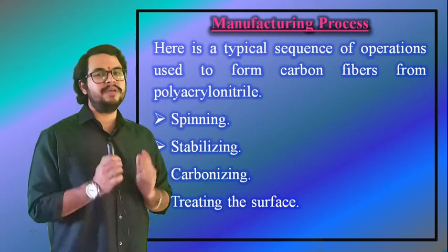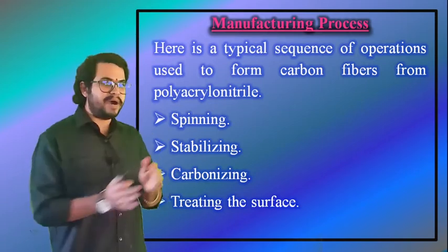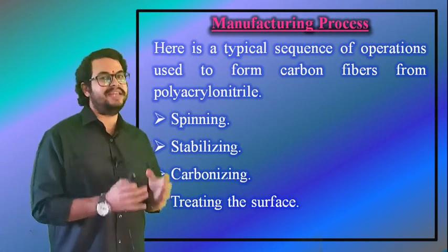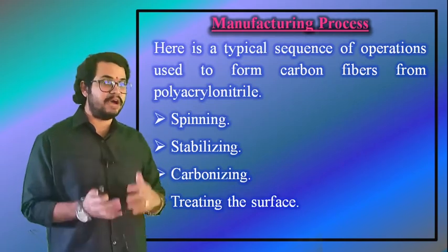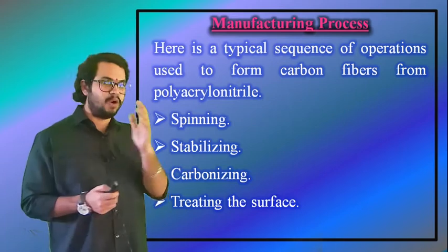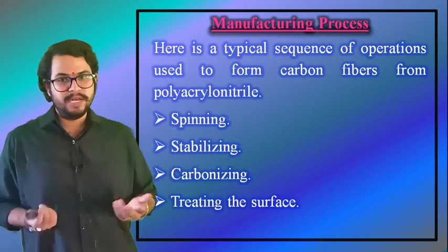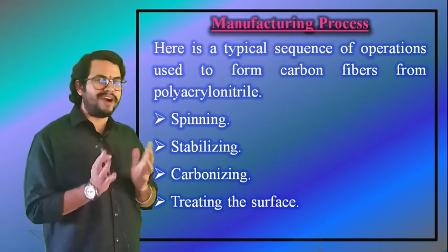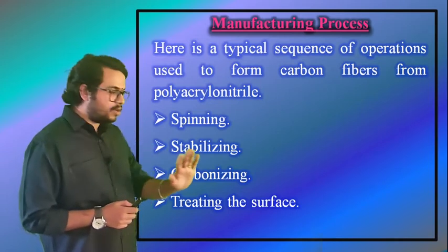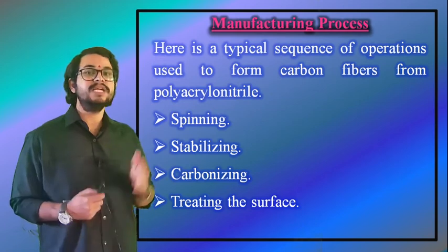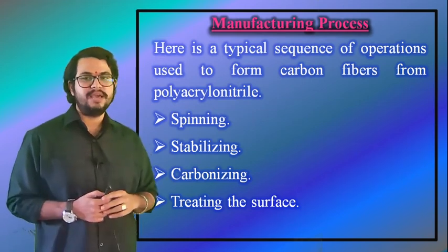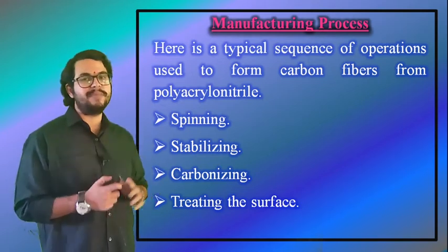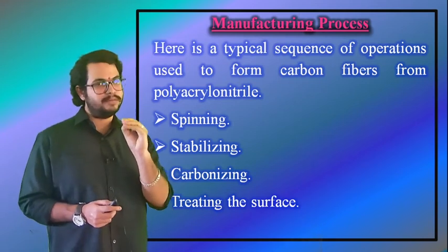The process for making carbon fibers is part chemical and part mechanical. The precursor is drawn into long strands or fibers and then heated to a very high temperature without allowing it to come in contact with oxygen. Without oxygen, the fiber cannot burn. Instead, the high temperature causes the atoms in the fiber to vibrate violently until most of the non-carbon atoms are expelled out. This process is called as carbonization, and it leaves a fiber composed of long, tightly interlocked chains of carbon atoms with only a few non-carbon atoms remaining.